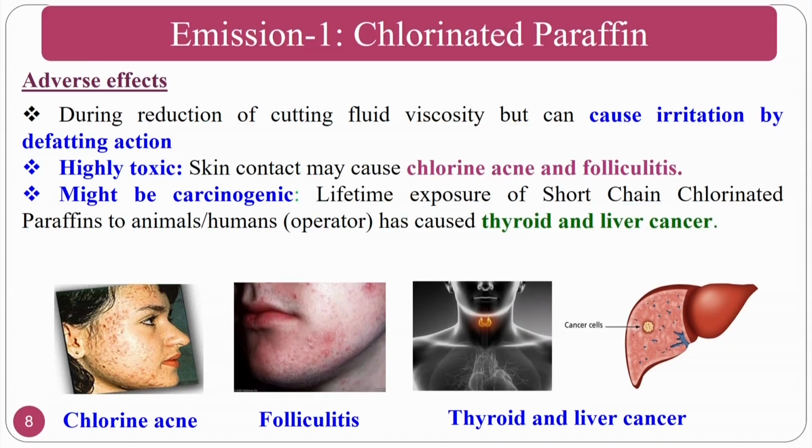That is why this is called contact dermatitis, because the chlorinated paraffins come directly into contact with the surface of your skin. The adverse effects follow like this. The chlorinated paraffins also cause other adverse effects during the reduction of cutting fluid viscosity, and also cause irritation by defatting action. So, what does defatting action mean?